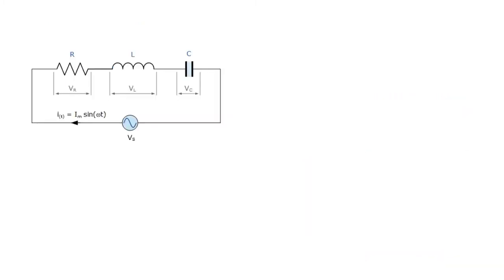What about the source voltage? This is the advantage of using phasors in analyzing circuits powered by AC sources. Phasors have two components, its magnitude and its direction. You can therefore treat phasors the same way as you treat vectors. You sum all the voltages in phasors the same as you sum vectors.